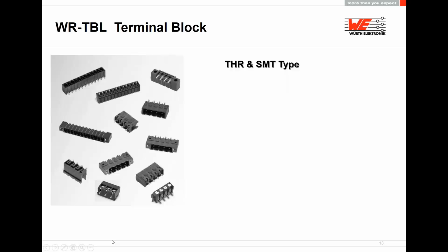Thermoblock, through hole, and surface mount type. From our end, when you see any thermoblock and it's black, that means it could handle the through hole reflow. Features, the pitch, we have 3.81 and 5.08 millimeter.